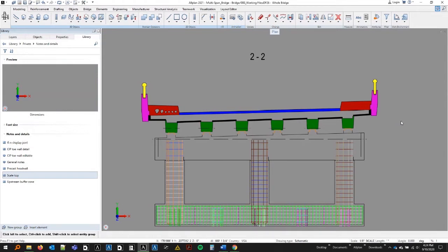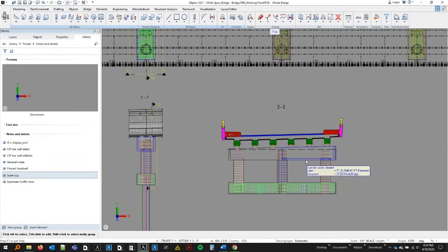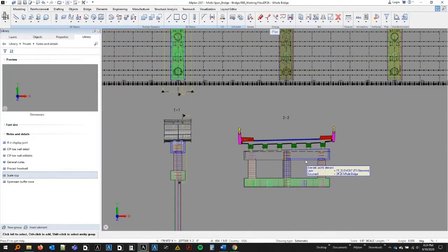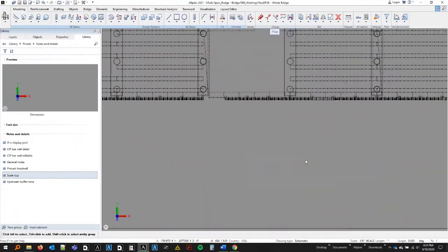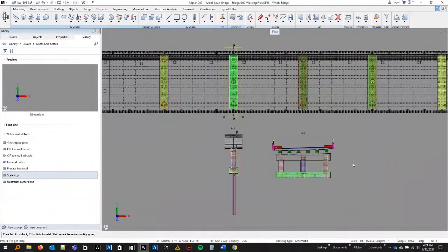I clearly see a bright color indicating that this is precast concrete of a 4 KSI mixed strength. I have some precast stay-in-place forms here of another strength, cast-in-place beams or other precast beams, perhaps cast-in-place slabs here. But a designer or checker, without even getting too zoomed in on it, can immediately tell exactly what attributes have been applied to each of these different objects.